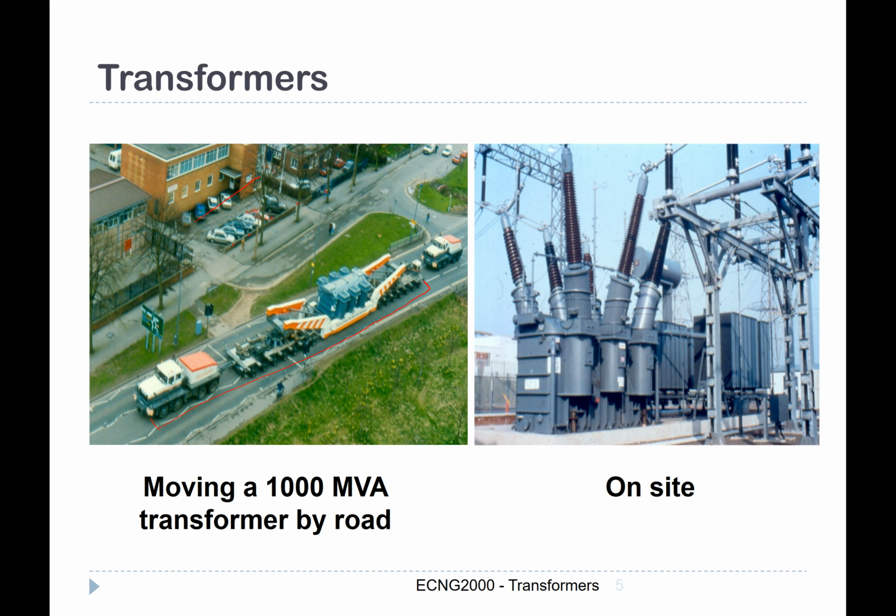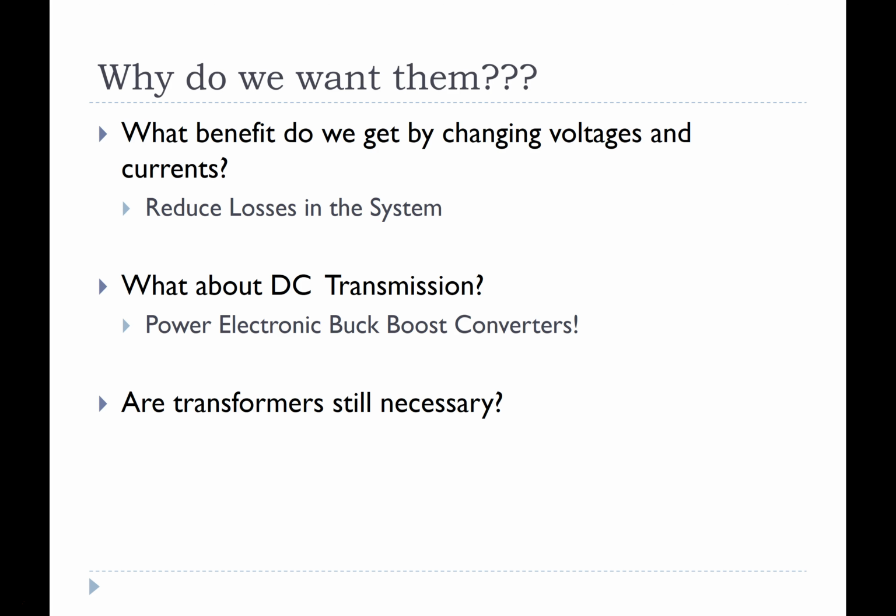So these pose rather technical challenges, not only in terms of their operation and how you use them, but also in how you get them on site, how you prepare your foundation and so on, so that they don't just sink into the ground. You can't just put it on a dirt foundation. So these are the kinds of devices that we are interested in, and for the purpose of this course, when we look at three-phase power, it is this size of transformer that we're really interested in.